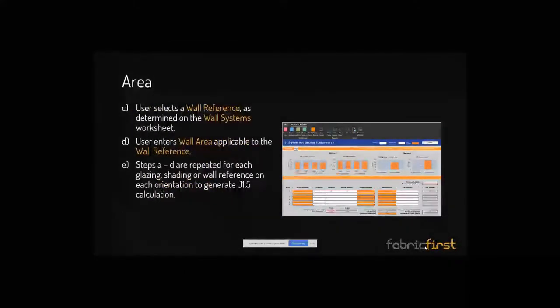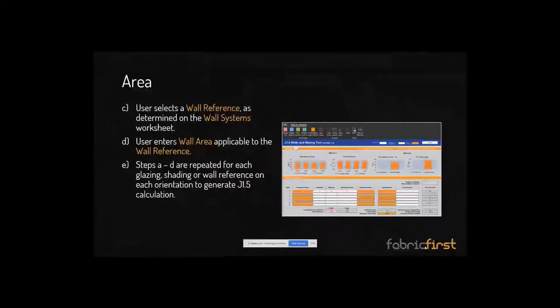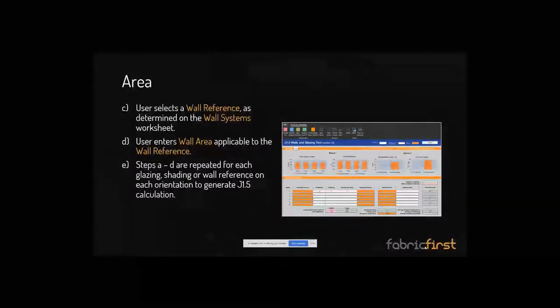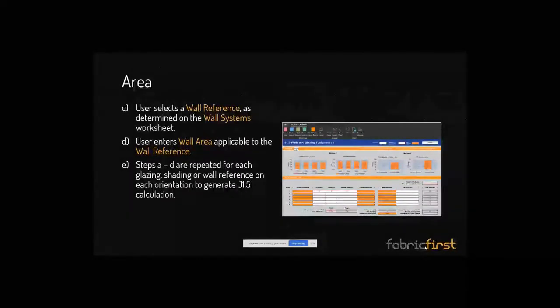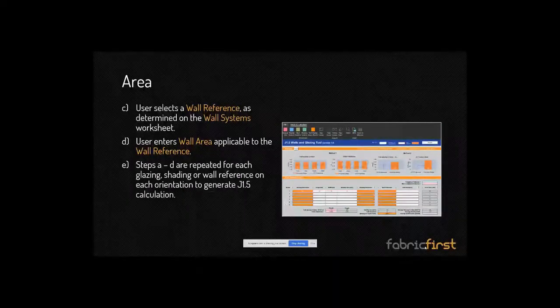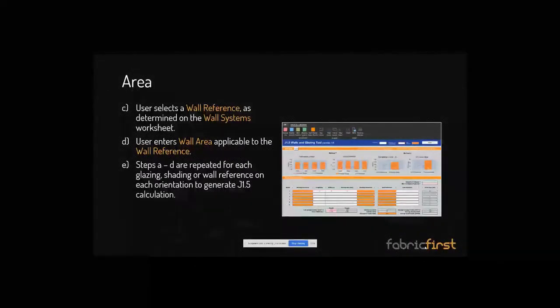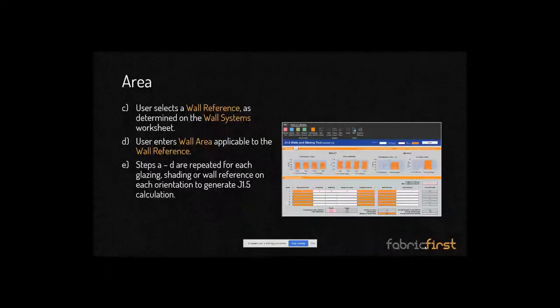So once you collate those, you pull them together. You can use the height and width to generate the glazing area, or just override it and just use the glazing area. Fire it in. You can expand everything. So you can put in, I think it was about 16 different references for each orientation in the end. So this is expandable. You're never going to need that. You'll start to go down a route of doing area weighting and being practical about what goes into this.